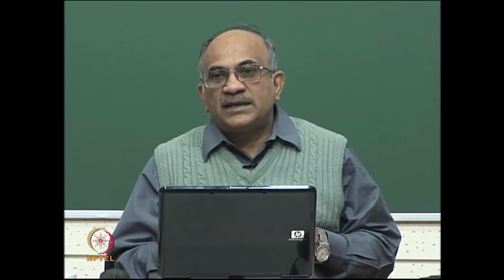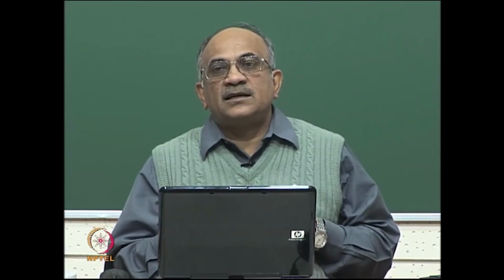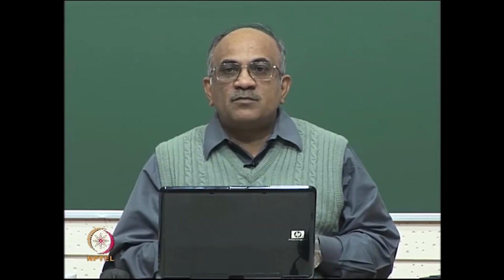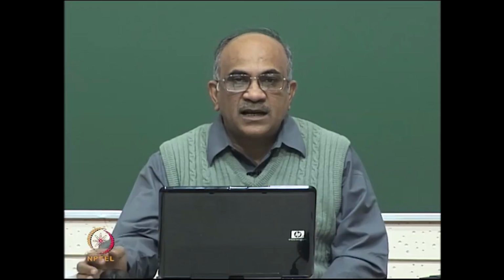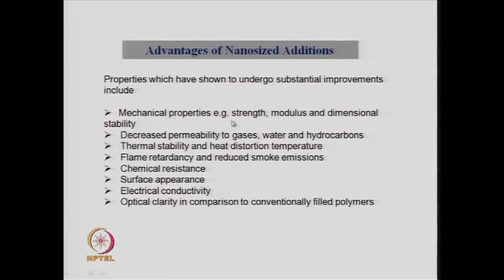So, the matrix gives it certainly several properties, but the most important property most of the matrices give is the mechanical strength and the stability. So, the mechanical properties, the strength, the modulus and the dimensional stability all are enhanced when you make nano sized additions to a matrix. Then the porosity is decreased, and because of decrease in porosity, the permeability of gases, water and hydrocarbons is decreased.